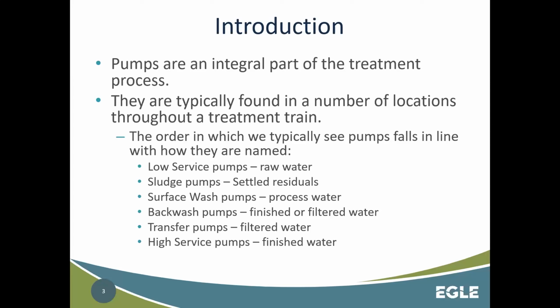The transfer pumps, right? We're transferring that. We use the transfer pumps to take that finished water and transfer it to a reservoir, usually a clear well. And then from the clear well, we'll go to high service pumps, right? The high service pumps are taking that clear well water and distributing it out to the distribution system.